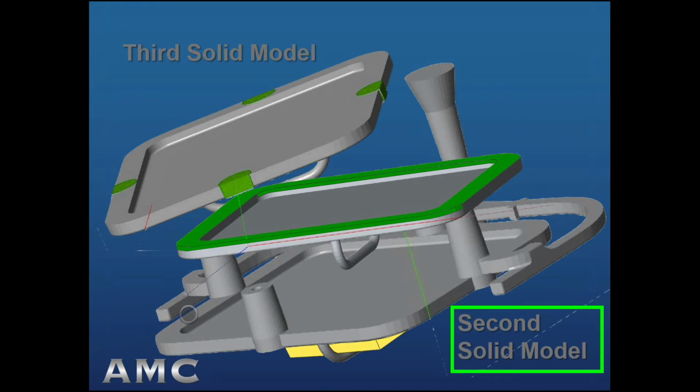And here we see the surface that has machine stock added for milling flat later with respect to datum A, which is the bottom surface. And then a groove will be machined across the rectangular profile for a seal ring.